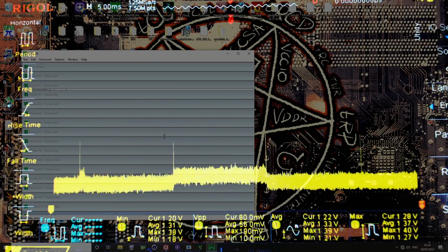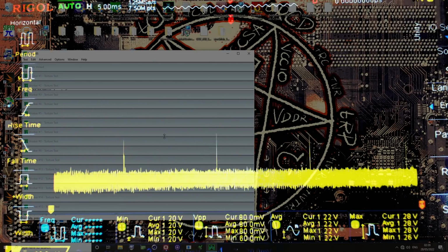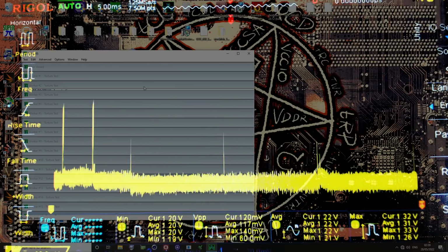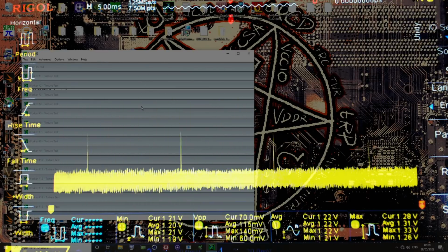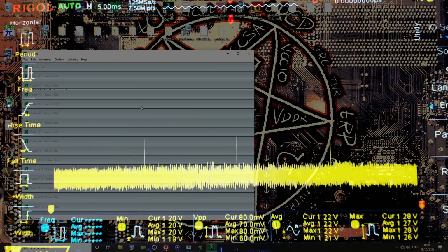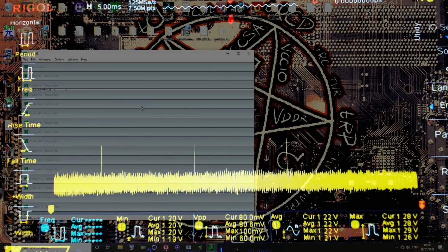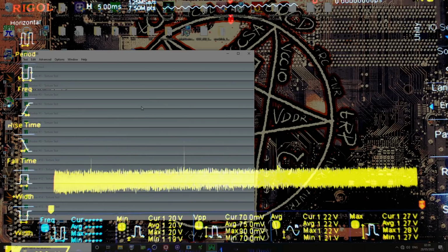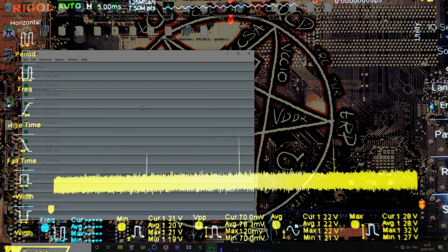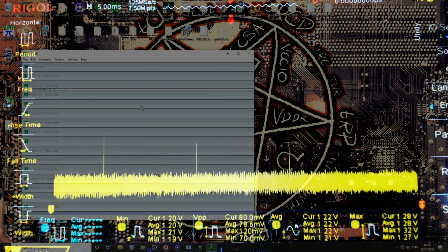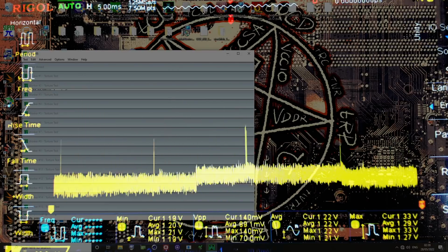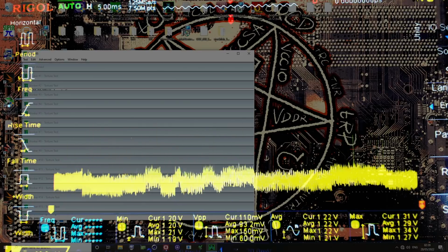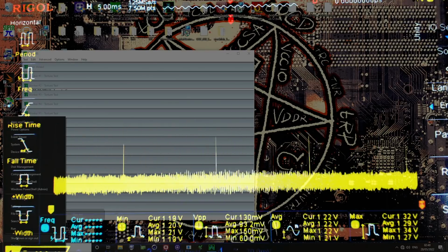600 kilohertz... It's nowhere near as bad. I wouldn't say it's great, though. At this point, I kind of suspect it's not getting worse, is it? If I reset the monitoring and don't touch the mouse, the minimum doesn't really get any worse, right? It's still dipping down to 1.119. If I move the mouse around, it doesn't get significantly worse, but the voltage still seems to be moving around a bit too much for small FFTs, in my opinion.